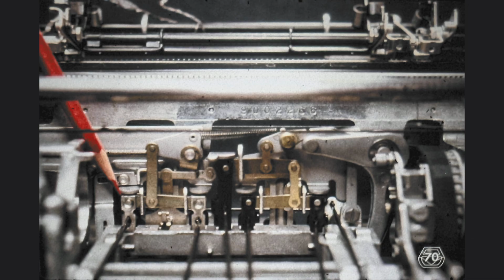2/3 of the motion obtained from the cam and transferred to the tilt pulley sector at the carrier will cause the type element to rotate from its rest position to the 3rd band of characters, counting the bands from top to bottom. As a final step in this fact-finding activity on your machine, you should hand cycle a J, and observe that for a J, both selector latches will remain under the positive latch bail.